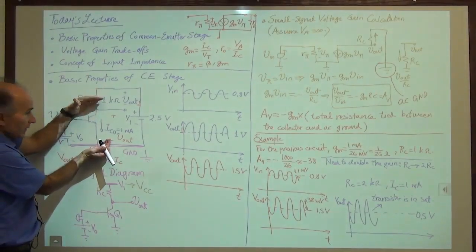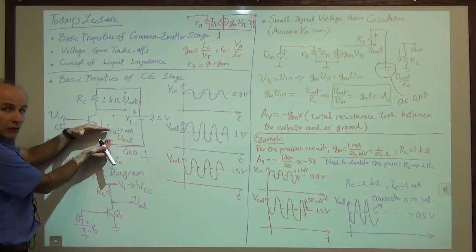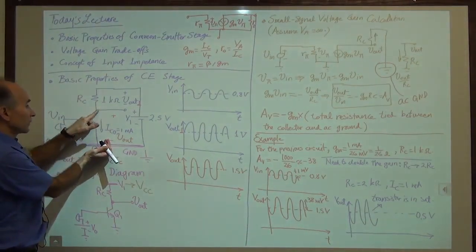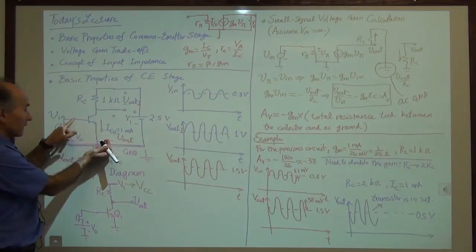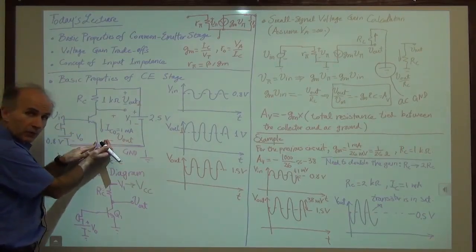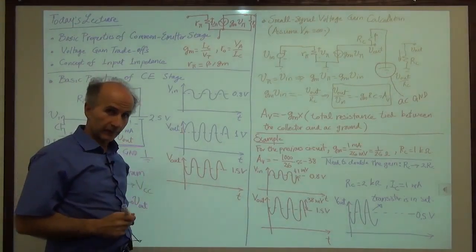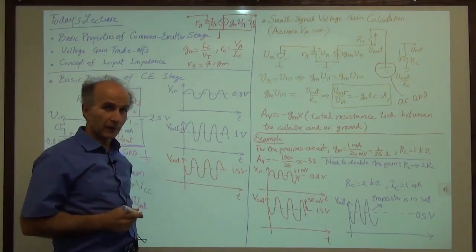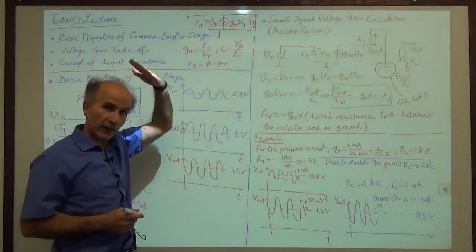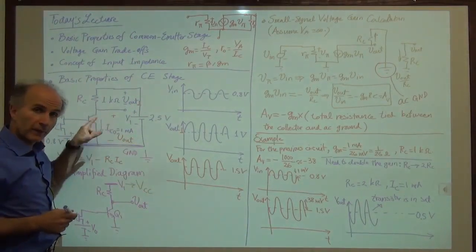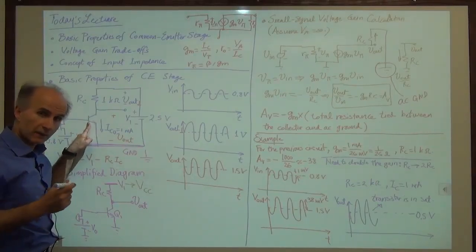As RC increases, this voltage shrinks. And eventually, we don't have enough room. We don't have enough headroom for collector emitter voltage to be at least equal to base emitter voltage. So we say the voltage headroom is limited. Headroom means how much room you have above your head, meaning how much margin do we have here before the transistor enters saturation.